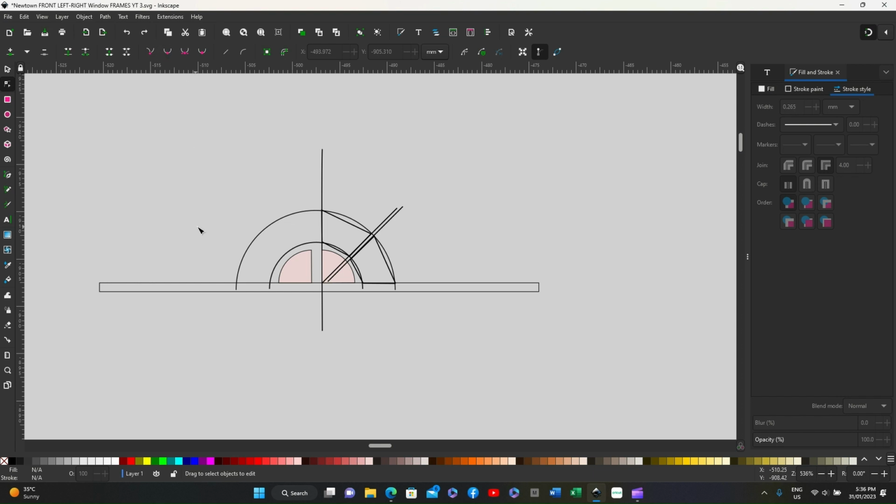So click on that. Now move into the box where you have the straight line, and it will highlight that, and a cross comes up in the center. Click on it and just move it, and it will move the handle to the path of the outer curve. Repeat that with the bottom, and as you can see, the top quadrant is done.